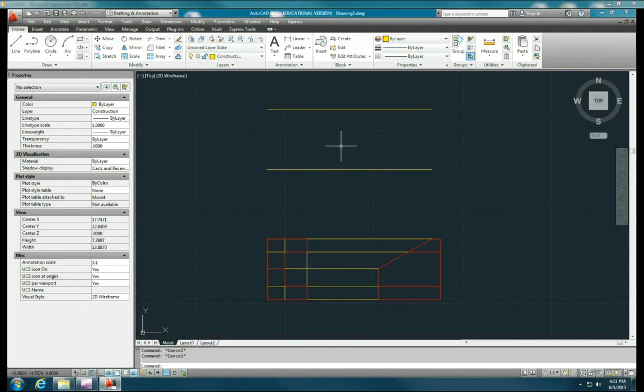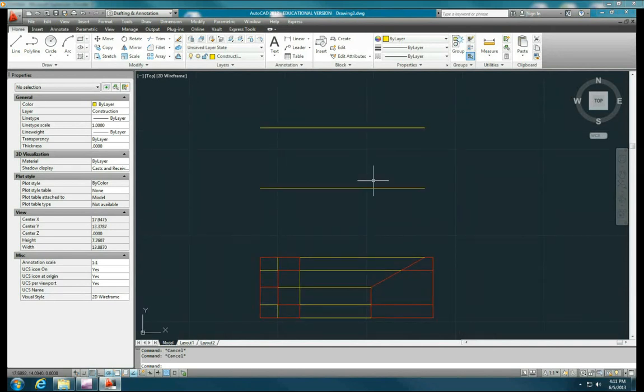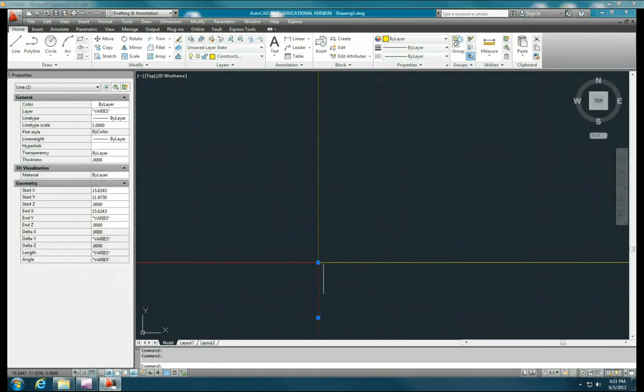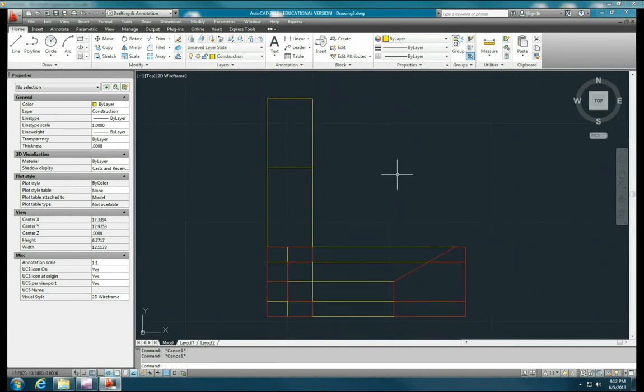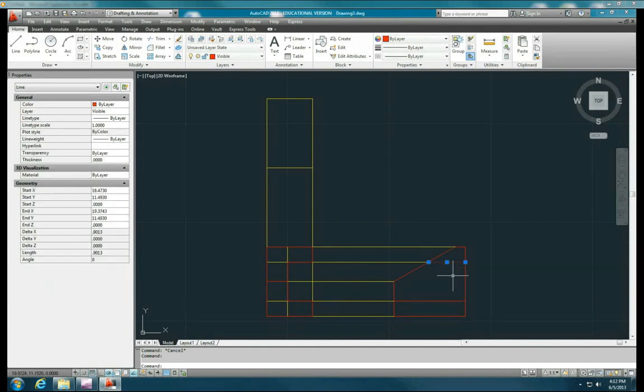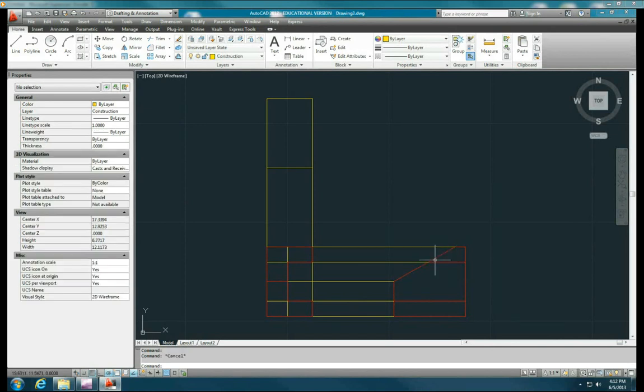I think that might be the only dimension we can take directly from the isometric sketch. So let's draw some lines up from the points of interest here, and then from here, make sure that's snapped on the end. Okay, I will trim off, TR, enter, enter. Let me trim that away. Now what we really need is this distance. Okay, we don't know actually what that line length is as given in the isometric sketch, okay, because it's actually determined by the 30-degree angle.